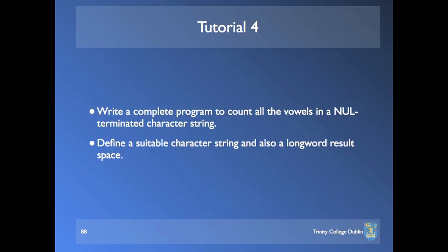Okay, so we're looking at the condition code register, which is part of the status register there. The bits of interest are X, N, Z, V, C. The other 3 bits, by the way, are reserved by Motorola, or they were reserved by Motorola for future expansion. And I don't know whether any of them are used in the 68020 or 30. I just can't remember. The system byte, there are 5 bits of interest in that, which we'll talk about in due course.